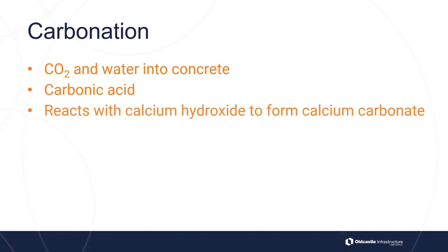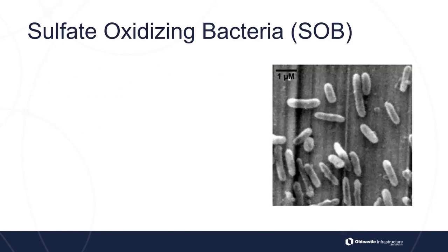So basically, the leaching of calcium hydroxide through contact with wastewater, along with the growth of other microorganisms, may also lead to a reduction in the pH level near the concrete surface itself. And once the concrete surface reaches a pH value of between 9 and 10, we see the colonization of Thiobacillus microorganisms, also known as SOBs. Now, I have to say that these are real SOBs. Sulfate oxidizing bacteria are the main issue and the main problem with MIC.